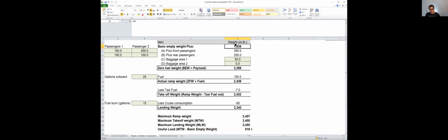So you need to use the specific empty weight for your aircraft, and that is going to be part of the documents that have to be in the aircraft. Remember your airworthiness, registration, operating limitations, weight and balance, all that has to be in the aircraft. So as you do your weight and balance, you need to use the empty weight that is specific for your airplane, which should have been signed by a mechanic that weighed the aircraft. Okay, any questions on that?